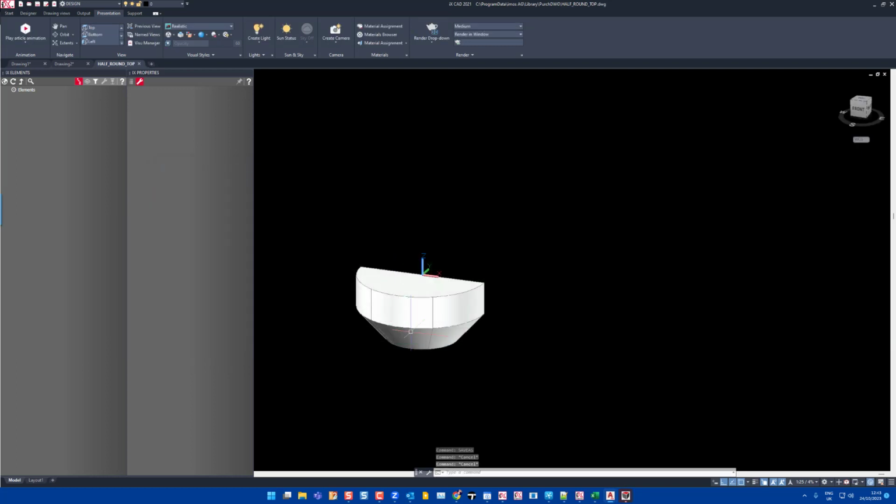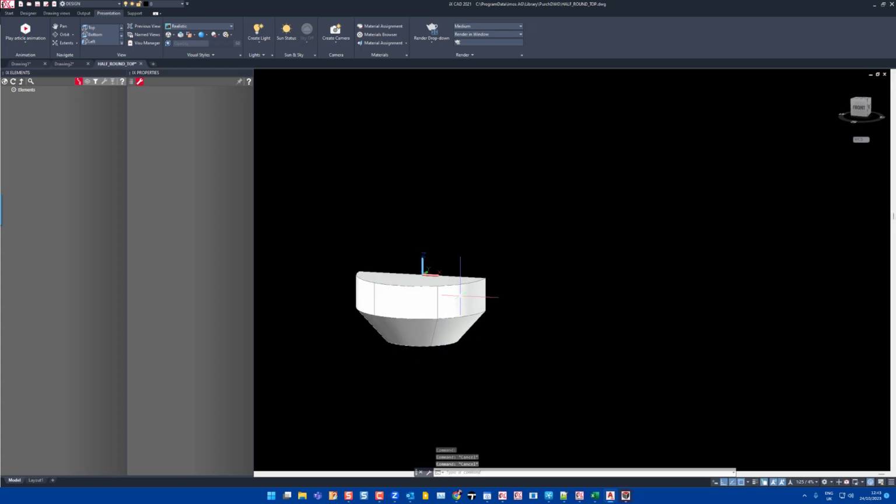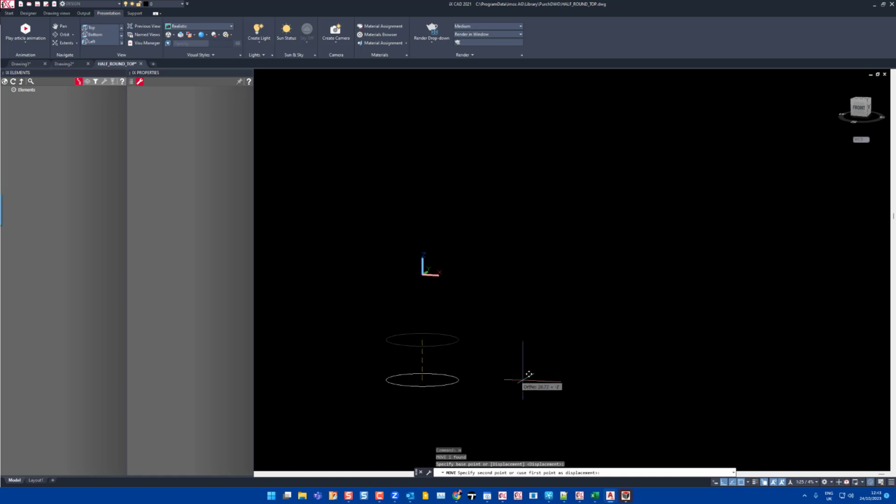Okay. The next thing I want to do is get this circle, and I'm going to say from here to here. I'm going to move that back up to my 0, 0 point. So I'll take my center point and say that that should be 0, 0, 0. And then I can draw a line that bisects this.